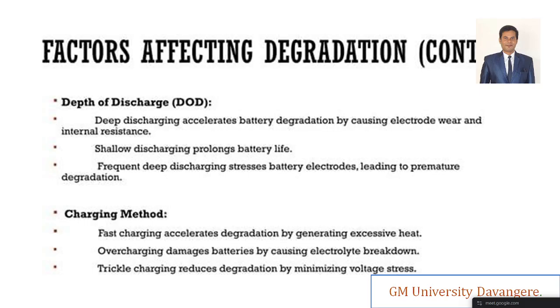What is the reason why you should go for overcharging once it is charged? Sometimes the EV may give a signal that it is overcharged, or else we have to make some kind of system to make people understand the battery is fully charged. It has to give some alarm for the users. If you don't use that kind of system, people will not have any awareness, and they'll keep it plugged in for long times. Then if the voltage is increased to 3 to 3.5 volts, it will affect the electrodes. The electrode will try to break down.